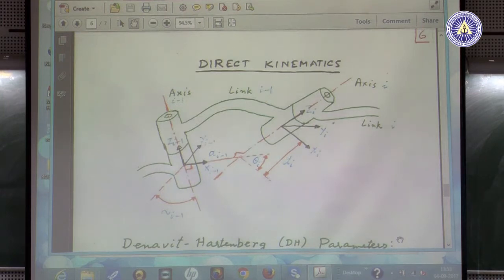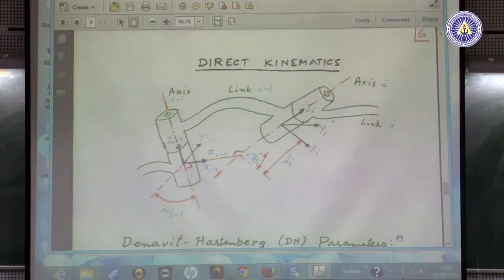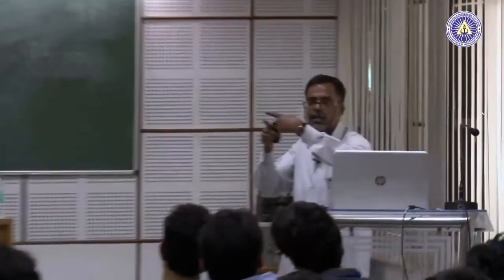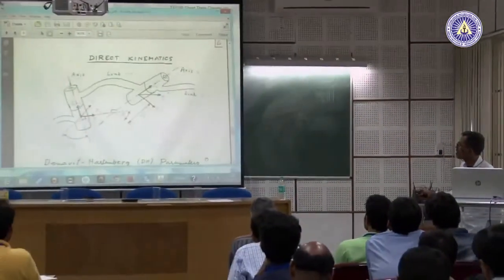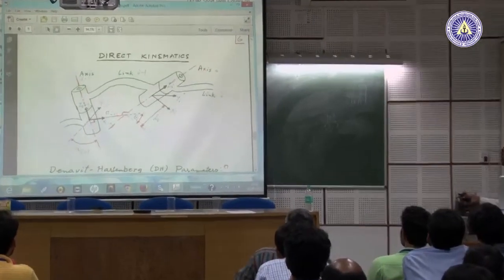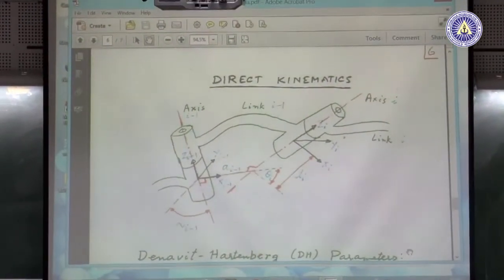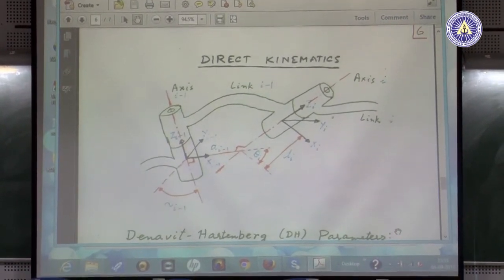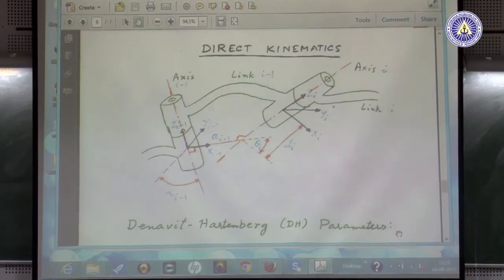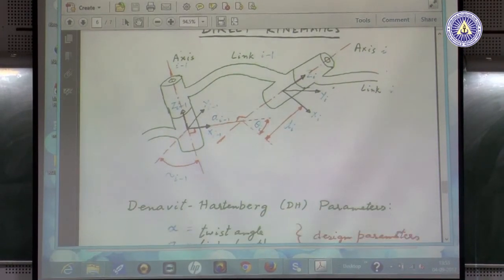So, one passes like that, another passes like this, and in that case there will be a perpendicular distance between them, with one foot of perpendicular at this end, the other foot of perpendicular at that end. That plays an important role, and compared to this line, this joint axis, if you want to represent this joint axis along with the corresponding frame of reference, then you will need 4 numbers, 4 quantities. Those are the most important numbers in manipulator kinematics.